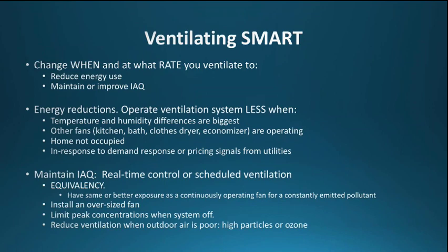But fundamentally, we need to maintain the same indoor air quality, which means we need some operational definition of what that means. And from this point of view, we call that equivalency. That is, having the same or better exposure as a continually operating fan for a continually emitted pollutant. That's the definition of equivalency we use with smart ventilation. There's lots of arguments about which pollutants that may not apply to, but we don't even talk about those at all when we talk about the dumb ventilation standards, so I'm not going to talk about that here today.